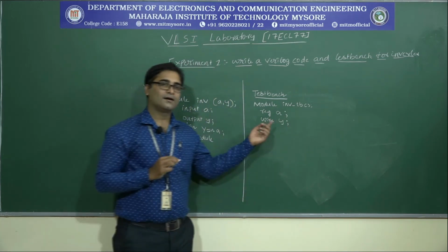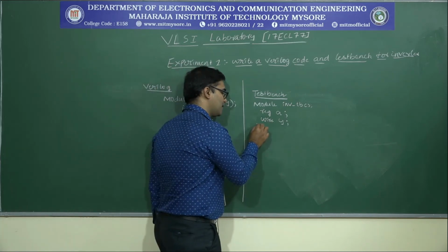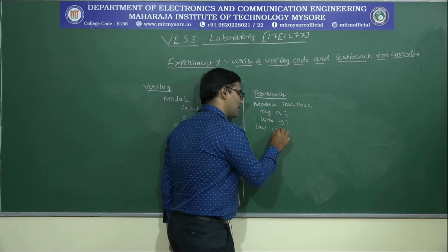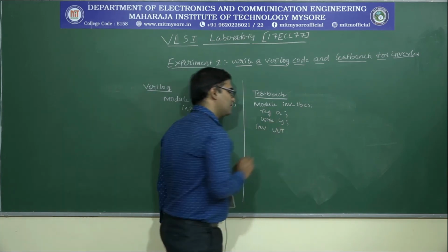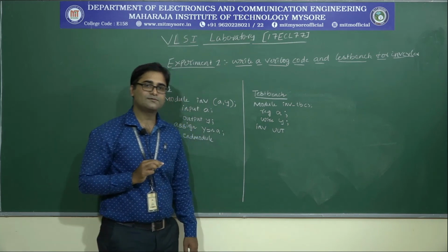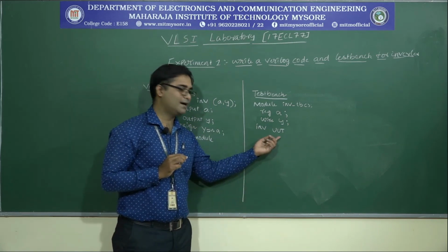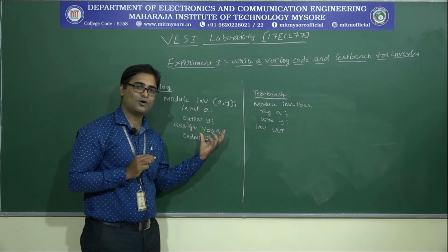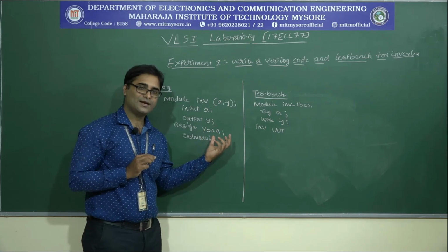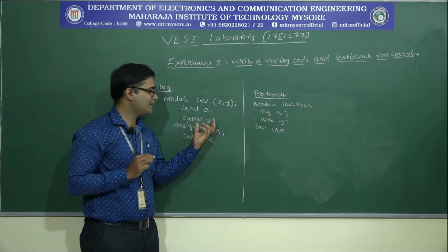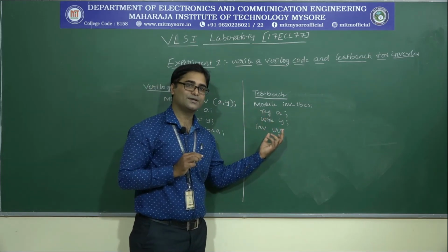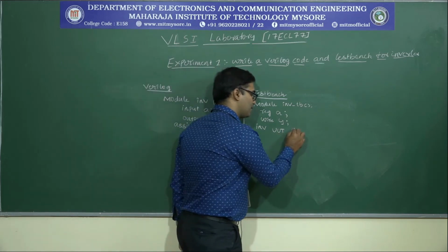The next instruction is the module name, followed by a particular instruction called UUT, which stands for the unit under test. We are testing the Verilog module to obtain the simulation results. So we are interlinking the Verilog module with the test bench inputs and outputs.